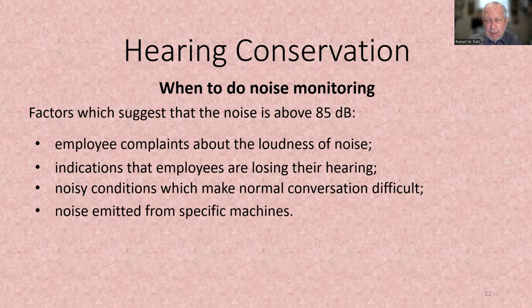We said, well, man, we have to do something about this, because we're going to have a hearing program if somebody's working, and somebody had to work near it. So we looked at it, and we did three things to it. We took it apart. I didn't do this, but my guys did. And we sent out the part that rotated to be balanced. So we had somebody balance it for us. That was number one.